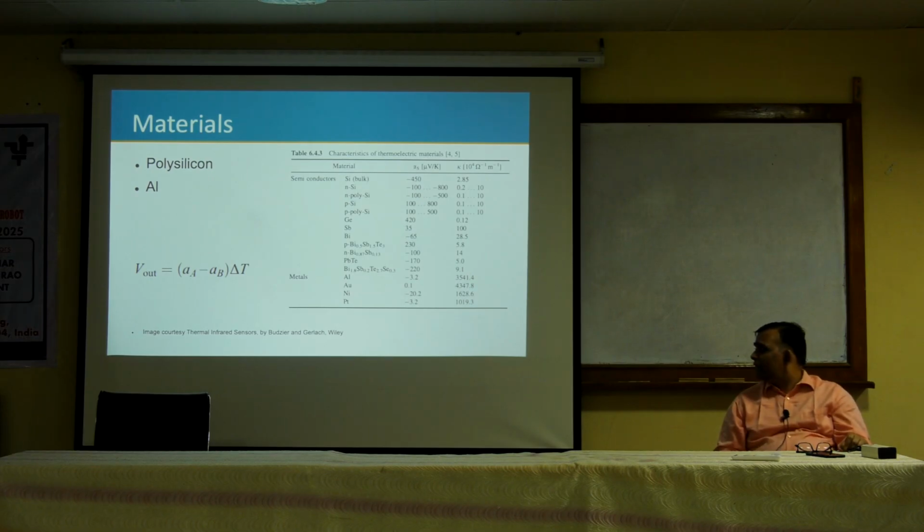The beauty of some of these metals: aluminum or gold is tricky to introduce in a CMOS foundry, because gold ions start diffusing in silicon and start changing the transistor properties. But yesterday, at least those who were doing layout saw we had metals, metal 1, metal 2, metal 3. In most larger processes, we used to use aluminum as a metal to connect transistors.